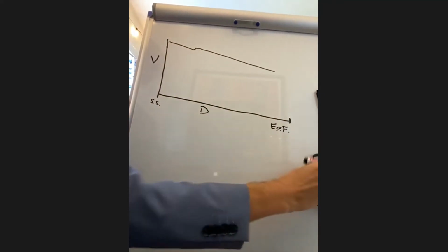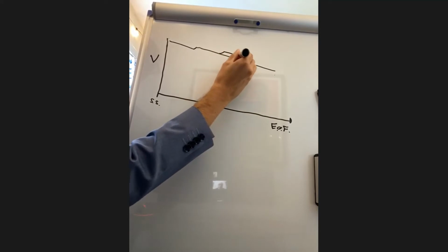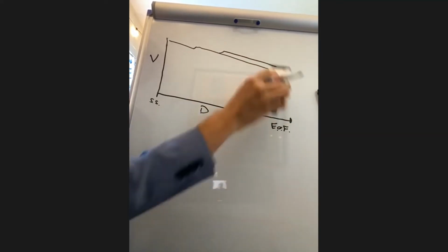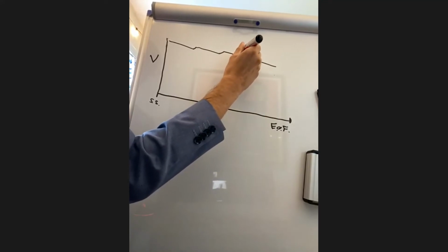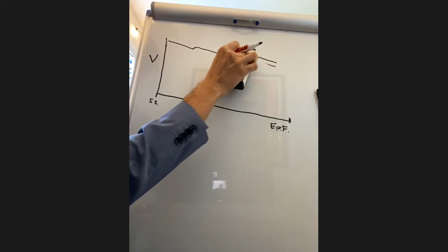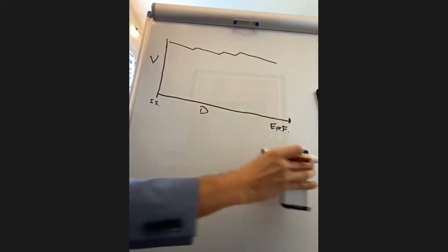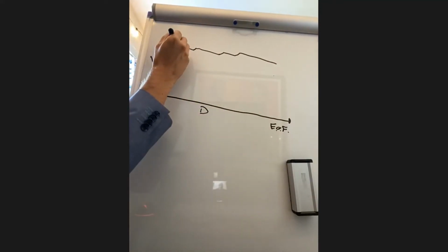And then if you had another customer down the circuit a little further install solar, now the spring scenario line looks like that. And then if you have another customer later injecting power, voltage continues to go up as you have more and more customers injecting power onto the grid. And utilities have a tight band by which they can serve power.